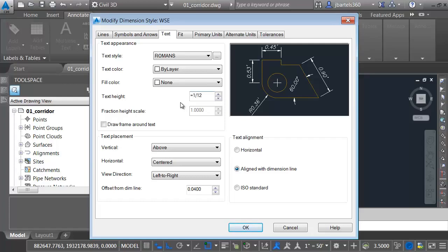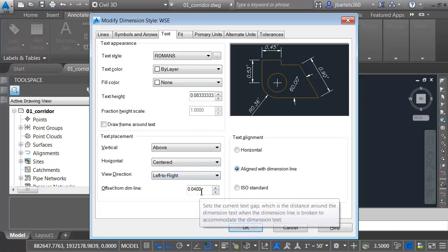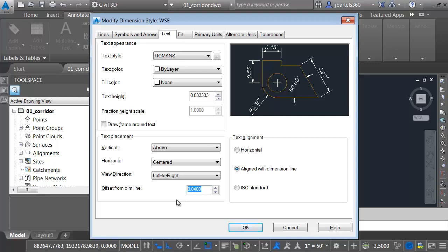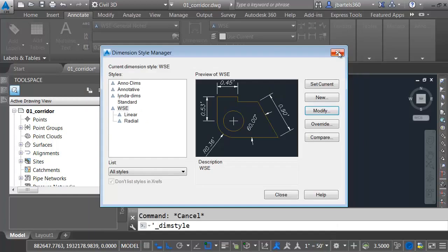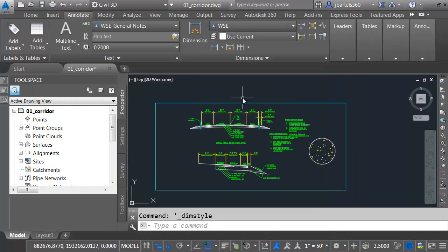And then I'll hold my Alt key and press Enter. When I do, it calculates that value for me. Let me come down in this one, just another one that is looking for a number, but I can type an expression if I want. Equals 0.5 divided by 12, Alt, Enter. Perfect. Let me close this dialog box. We'll close this. Now that was an AutoCAD dialog box.